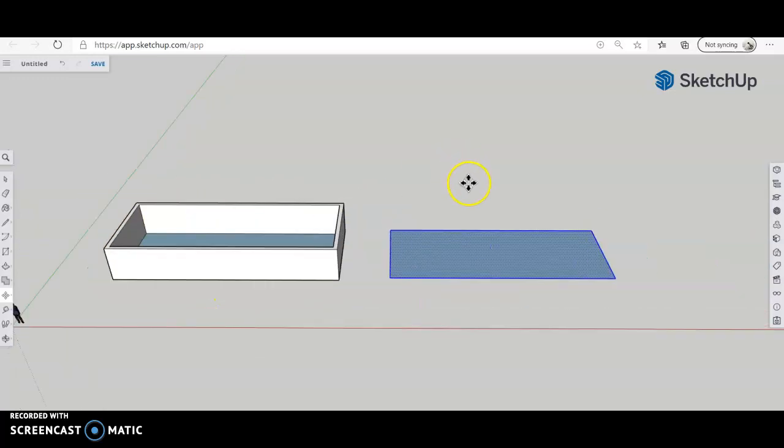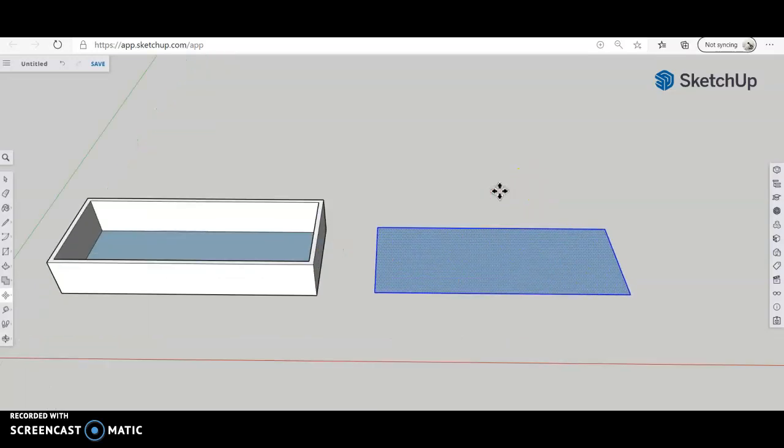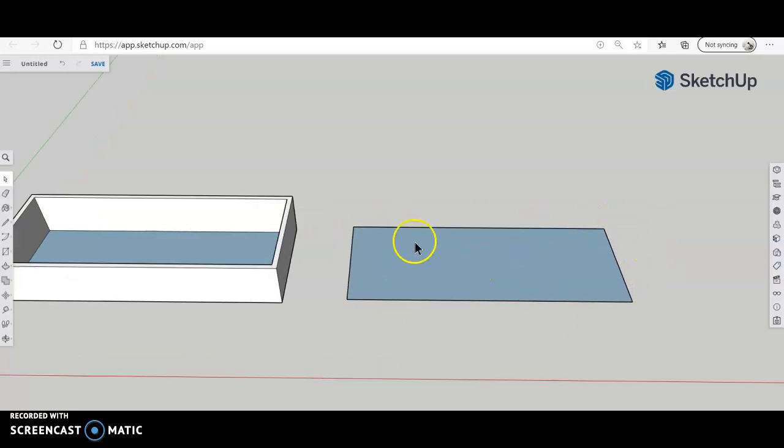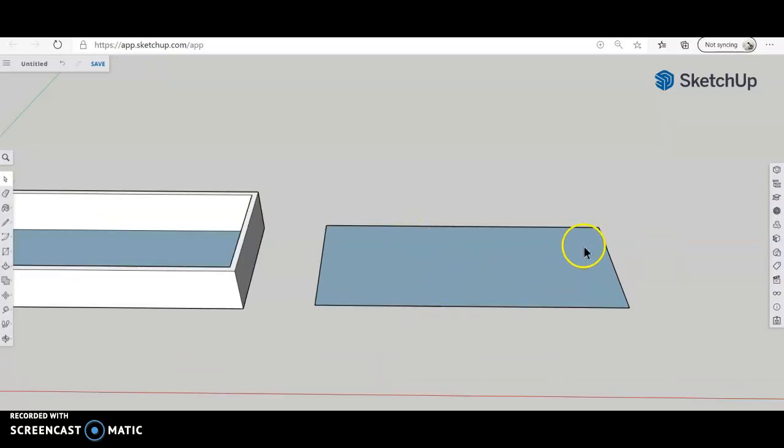Okay, so then what I did on the side is I created my roof separately from my actual house. This way you can take it off and put it on, right? You're going to make it a component. Okay, so what you're going to do is I just created a second 50 foot by 20 foot rectangle here. Okay, and we're going to make a roof using this.